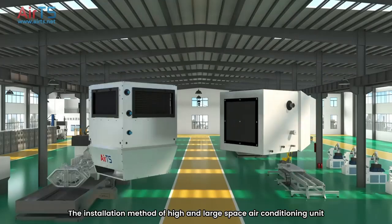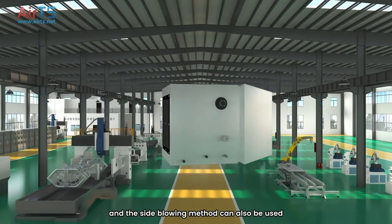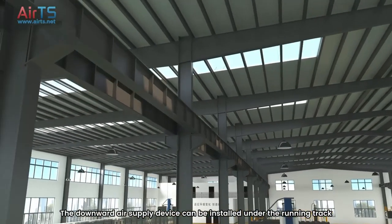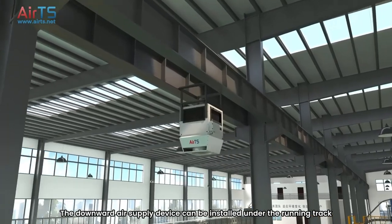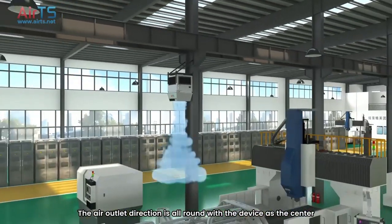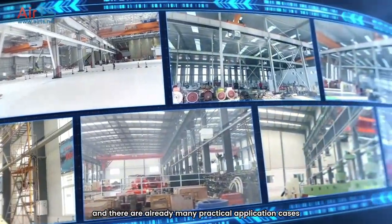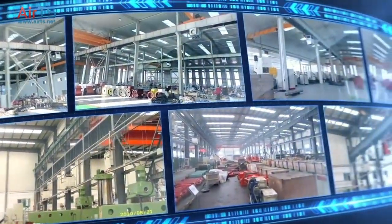The installation method of the high and large space air conditioning unit can be handled flexibly in practical application, and the side blowing method can also be used. The downward air supply device can be installed under the running track or on the column, similar to the jet flow unit. The air outlet direction is all round with the device as the center. It is much better than the one-way air supply of the jet flow unit, and there are already many practical application cases.